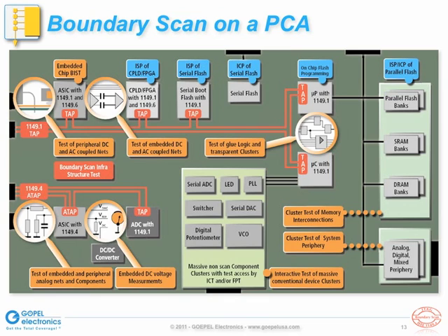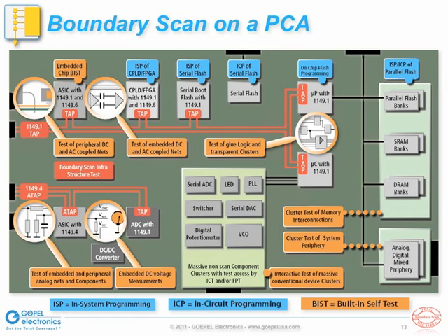In order to test interface circuits that are connected to boundary scan devices on one side and to peripheral connectors on the other side, additional tester resources would need to be wired to the peripheral connectors. These tester resources can then be used in conjunction with the boundary scan I/O on the UUT to stimulate and observe the interface cluster. In addition to test applications such as those discussed so far, we can also download firmware and other data into programmable devices using the scan chain as a transport medium.